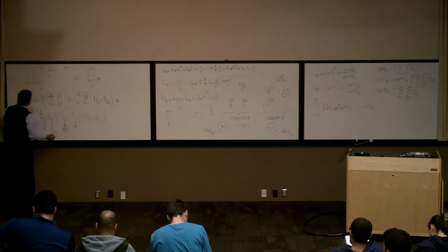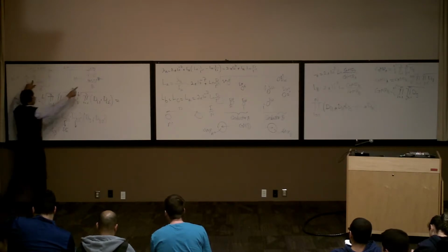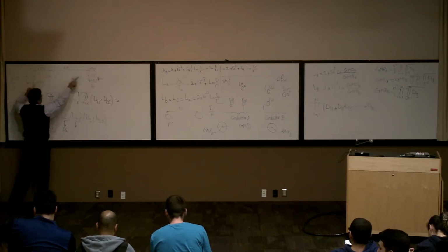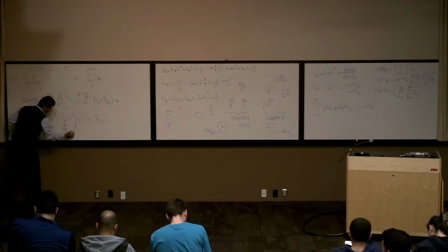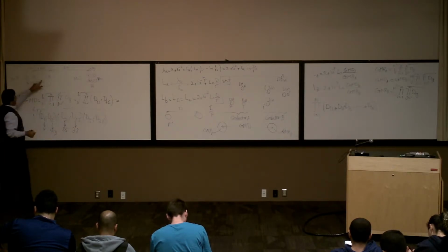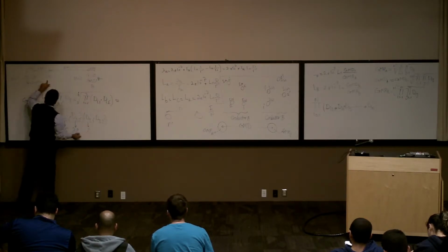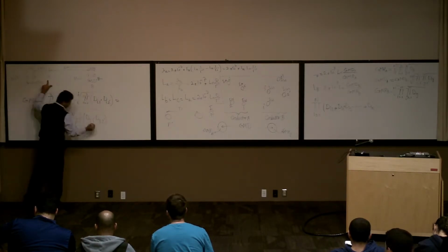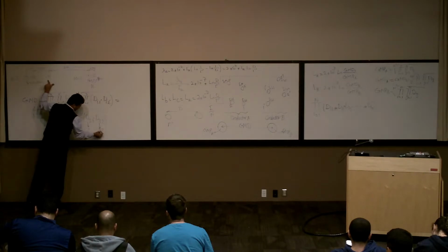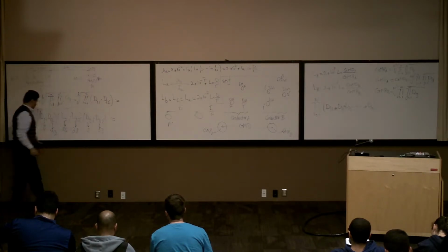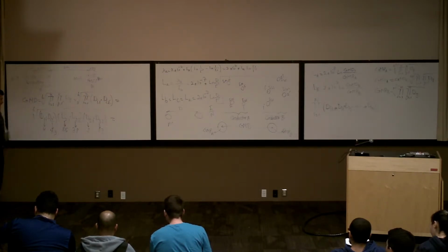How much is d22', from here to here? 3.5 and 0.3 is going to be 3.8. d31' is 2. d32' is 2.3. Right? So basically, you multiply all these things and calculate here to see how much the GMD is.